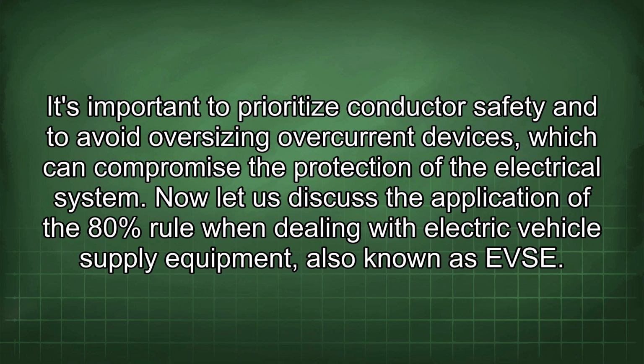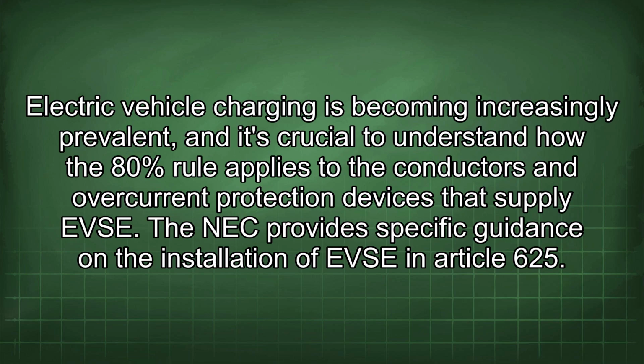Now let us discuss the application of the 80% rule when dealing with electric vehicle supply equipment, also known as EVSE. Electric vehicle charging is becoming increasingly prevalent, and it's crucial to understand how the 80% rule applies to the conductors and overcurrent protection devices that supply EVSE. The NEC provides specific guidance on the installation of EVSE in Article 625.